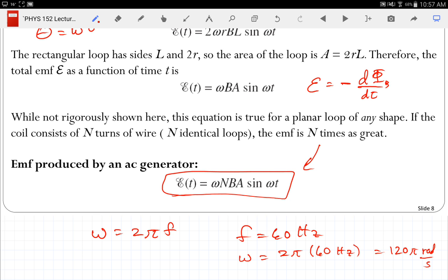And so the clocks in something like the microwave, because in America our frequency is very well regulated, a lot of things like our microwave ovens simply use the frequency of the electric waves to determine the time. Well, since the frequency kept jumping down every time some appliance turned on, what happened to the clock in the microwave? It was always slow. I think they said they lost like an hour in a day or something like that because the frequency keeps jumping down. It was really interesting, after teaching physics for a while, going and looking at it, it's a lot more interesting to me because I've talked about all of these pieces and now I see actual practical application. It's almost like I've been there.